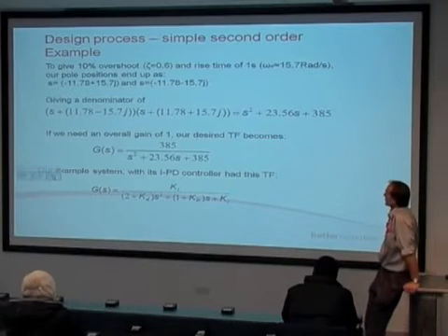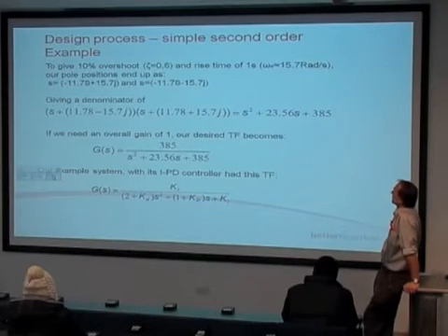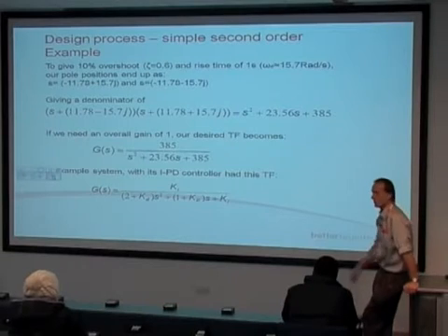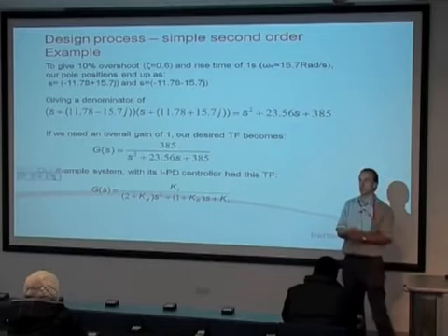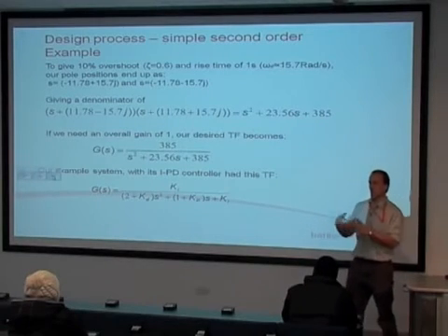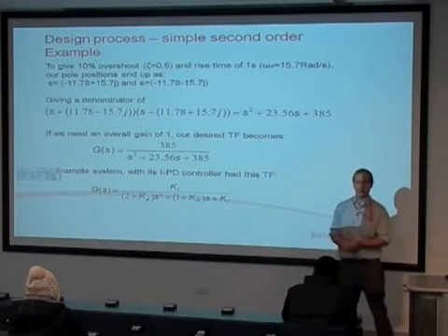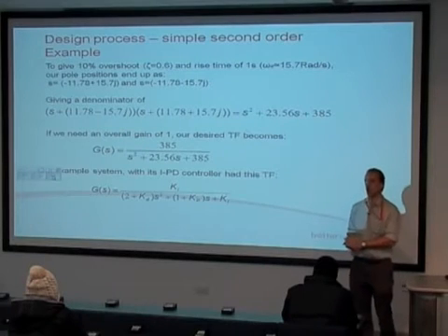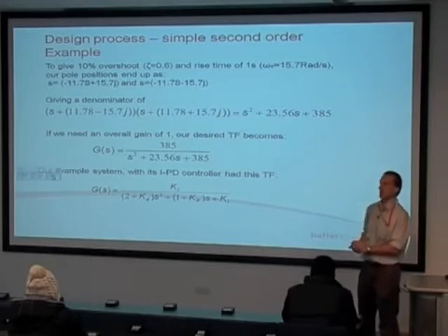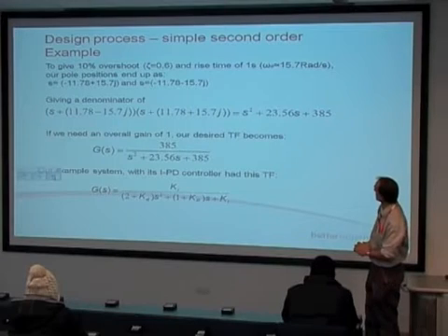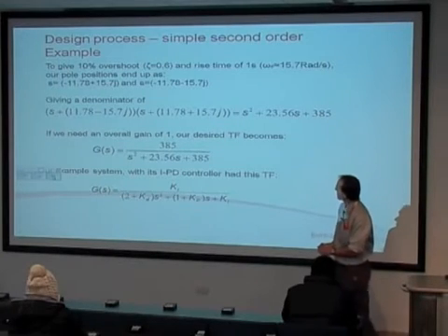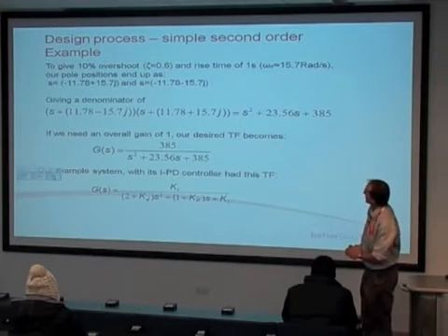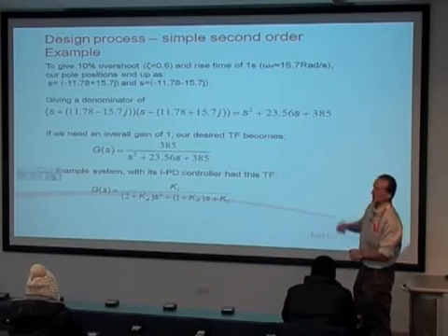This example is based around a rise time of 1 second. And if you recall, the rise time is approximately 1/4 of a period of oscillation. So the period of oscillation will be about 4 seconds. So the frequency would be 1/4 in hertz. And if you translate that to radians per second, we get around 1.57. So our pole positions would end up as those complex numbers.